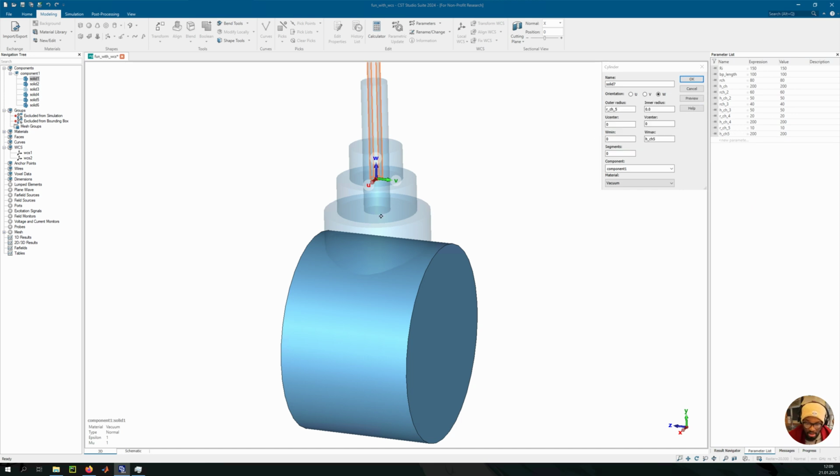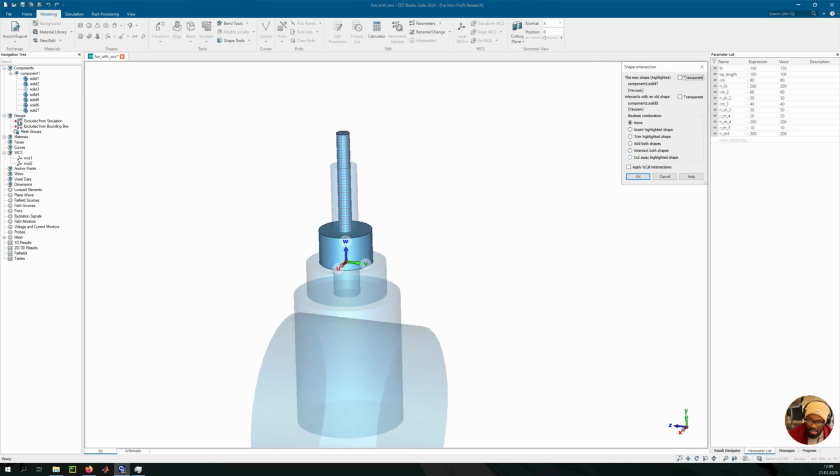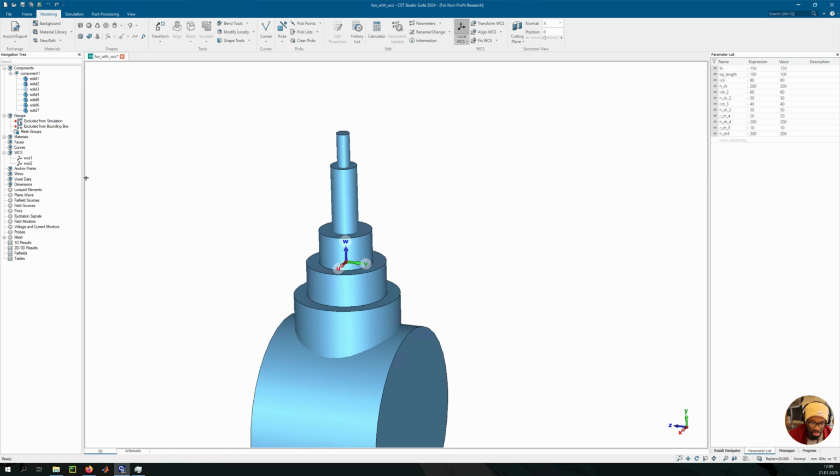So you see, it starts from this new coordinate system, and that's basically how you stack up. So if you had, I don't know, a million world coordinate systems, then for you to specify a coordinate system as the local coordinate system, you have to first restore it, and then it becomes the default local coordinate system. That's how you toggle between coordinate systems.